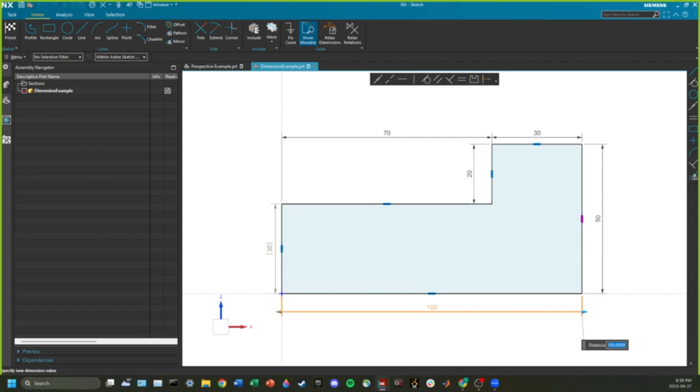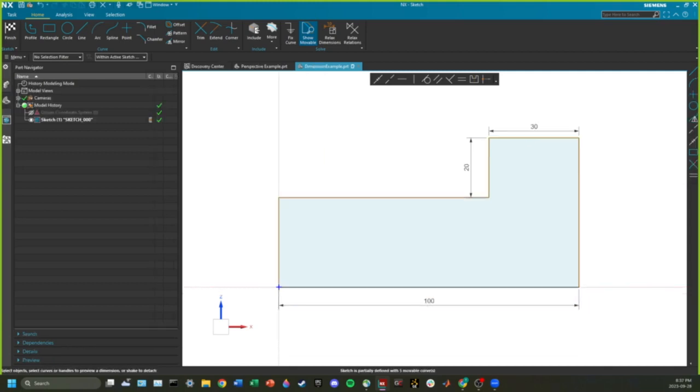So just keep in mind where you're putting dimensions, and you shouldn't dimension your entire part because when you try to change one of them, you'll probably break something. So something better, if I was doing this, it's a very slight change.